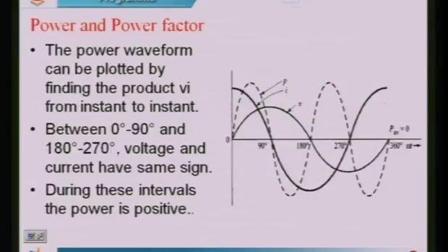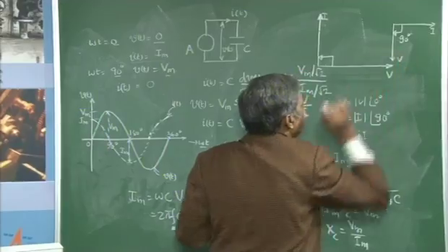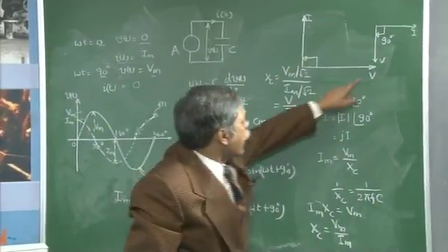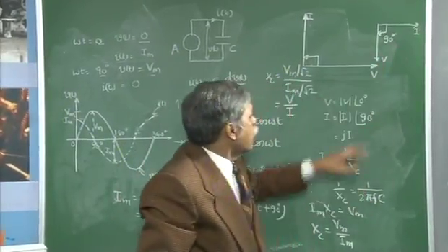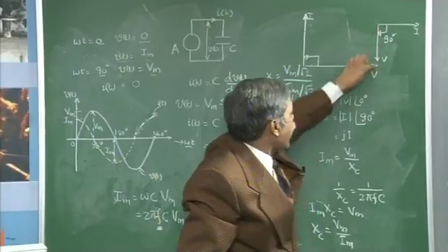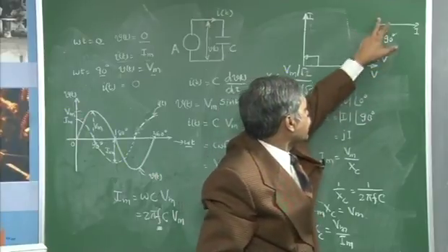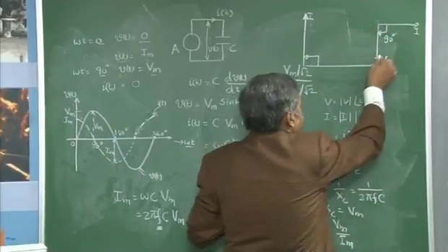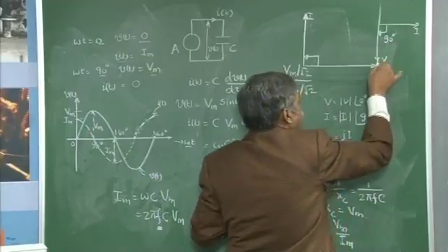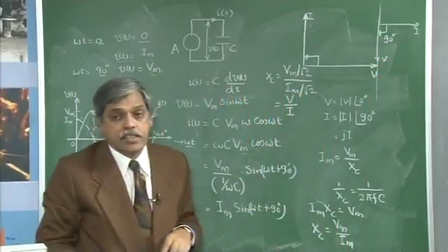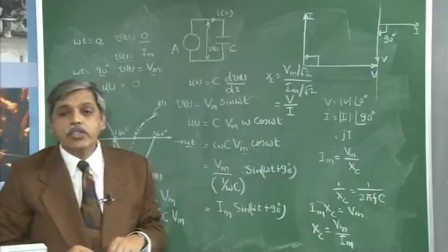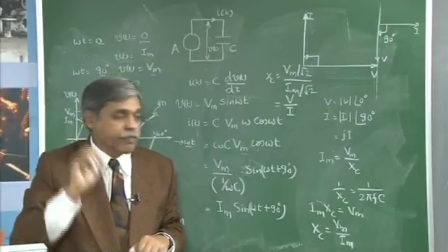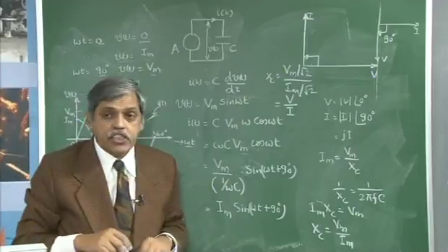Here also, as per the second diagram, when you have the voltage lagging behind the current, because this is the negative imaginary axis, the vertical axis what I have, the voltage is along the negative vertical axis. Therefore, I will be using the letter minus j before the voltage.